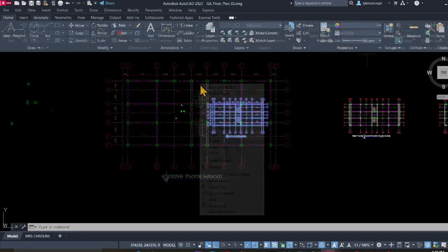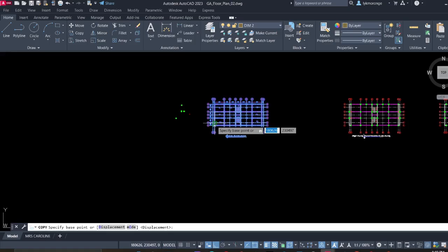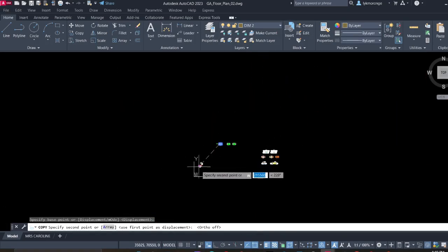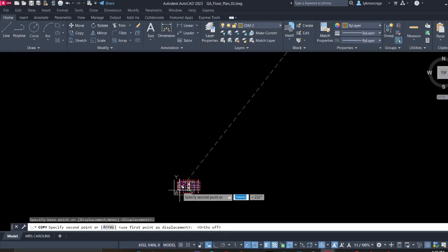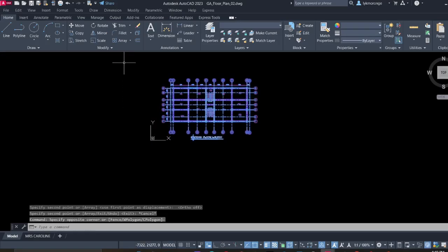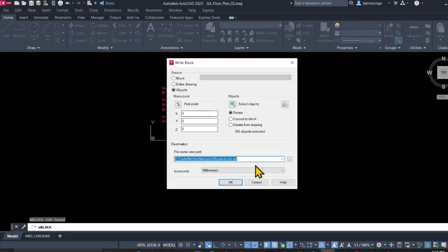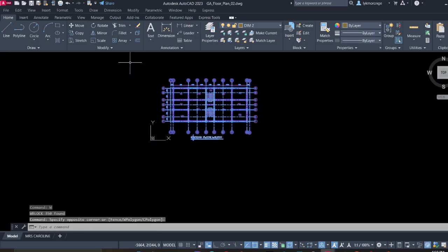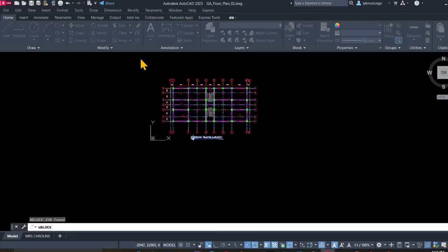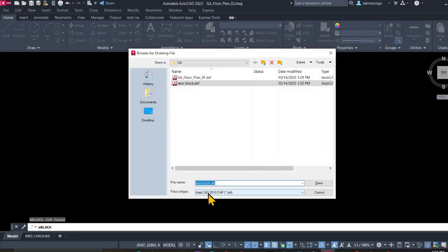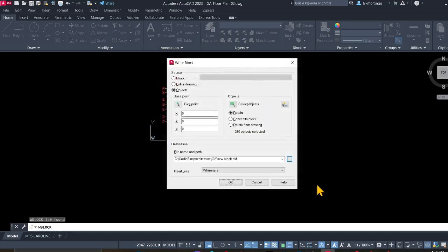So to do that, you can actually see how it will look like. Just copy this, just move it, or just remove the auto mode and bring it very close to the origin here. So we want just to bring it as close as this part here. Once we bring it closer to the origin, you can select the entire of it, write W, and then enter. With that, enter, simply say save. Okay, maybe we didn't actually note that. Just right click, enter, save, and save. Make sure that your units are in millimeters, and maybe the version of AutoCAD that you are saving is 2018, which is okay. So just click and say save.